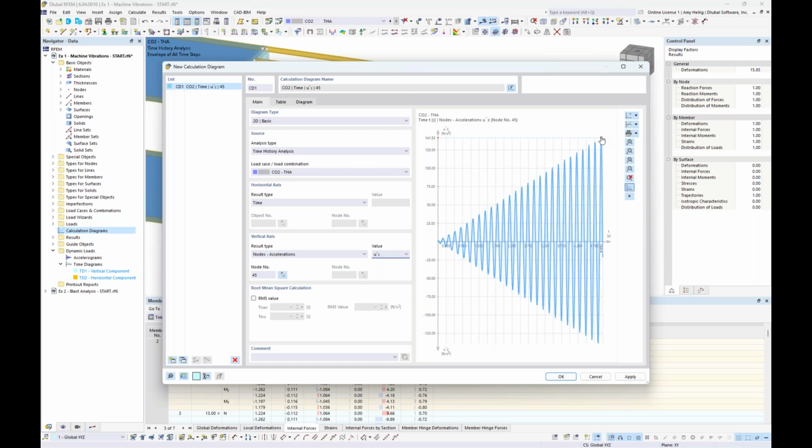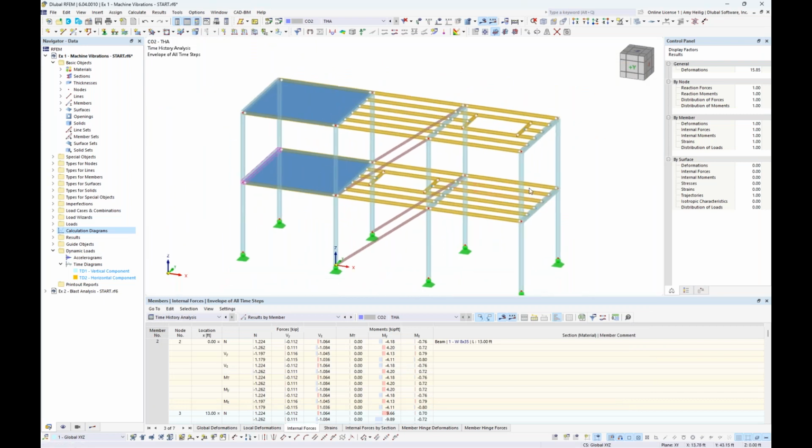But somewhere at the low end, it should be around 0.5% g, and somewhere at the higher end of acceptable tolerance values here is 5% to 10% g. But in any event, we are far over that with this particular structure. So we need to make some modifications. And the first thing that I would suggest doing is to consider damping.